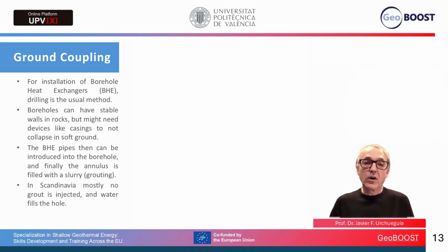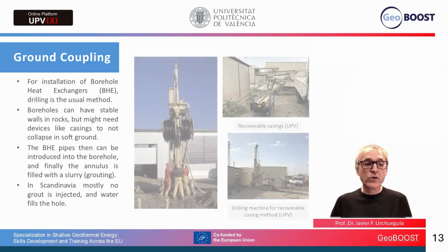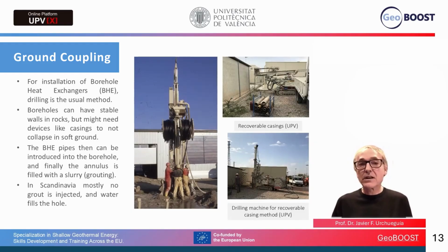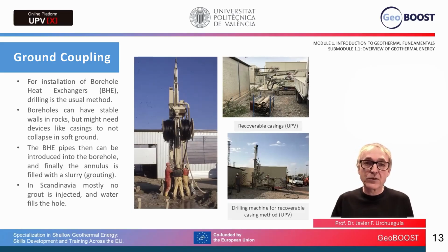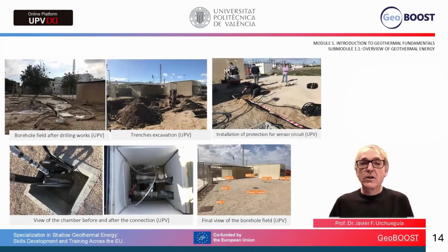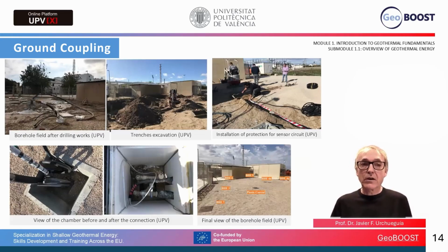avoid the collapse. Also, we have in Scandinavia and in the north of Europe some types of systems in which the borehole is just filled with water. This water is turned into ice and has a good conductivity. But these systems cannot be used in the south of Europe, where the temperature in the underground would prevent the water from forming ice. We can also look at other typical questions which arise when we install a ground source